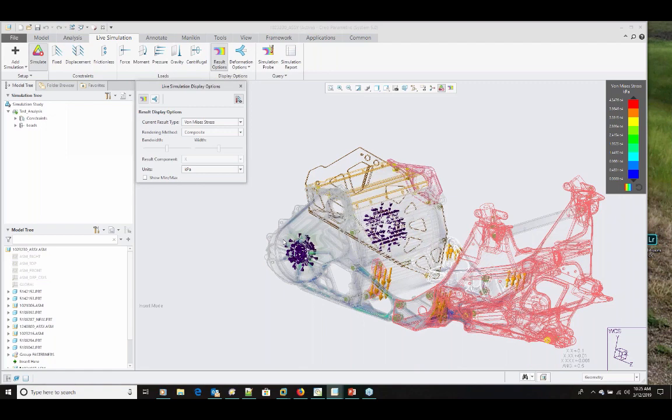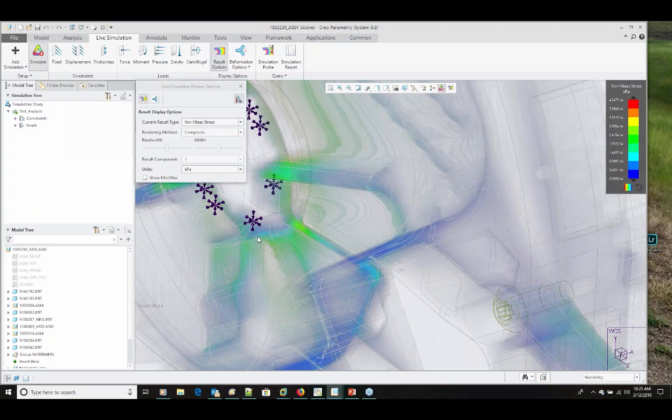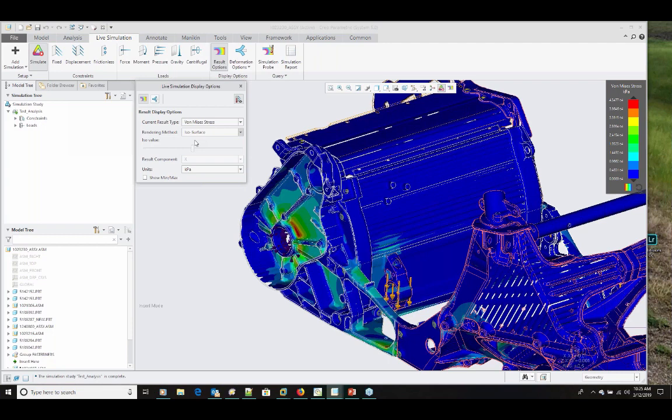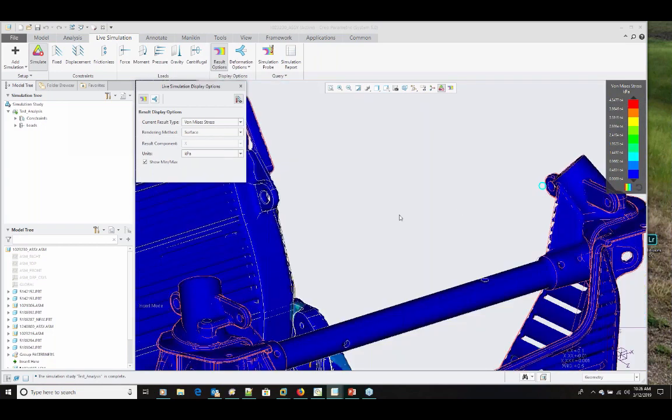Again, you can control what's being shown on those surfaces of constant stress values displayed here in the fringe plot. And if you want to show the min and max, I'll give you a couple of little circles that show the maximum value at that location in the model. Over here on the other side is your minimum value. So that's the global max and min.